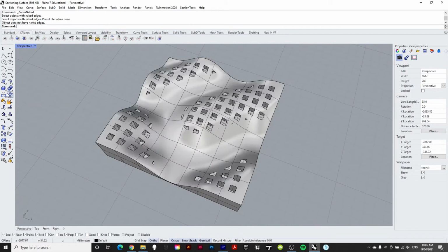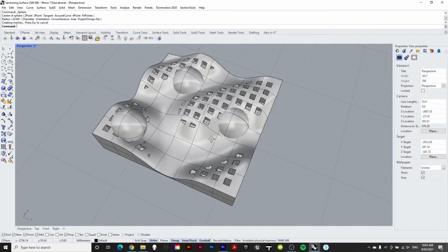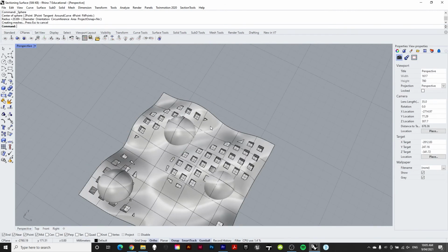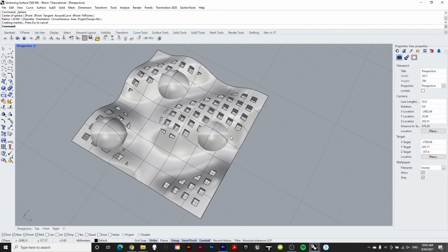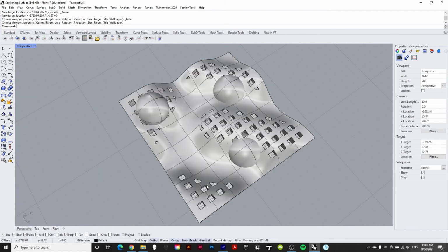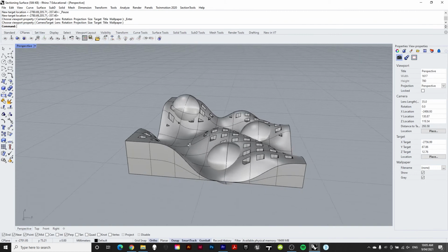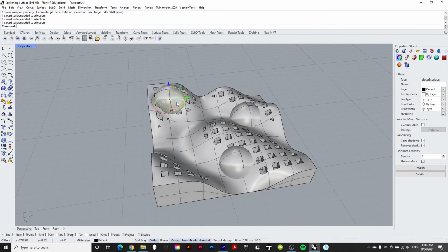Another thing that might occur as an issue for you is, let's say your geometry is actually made out of multiple closed surfaces. Now, in order for our CNC to be able to understand that, we of course need to do a boolean first. So what we will do, let's just place our camera so we can see what we're doing first. Place target on here. So we've got these different surfaces inside here, different solids. Each one individually is solid and ready to go, but collectively they're not solid.